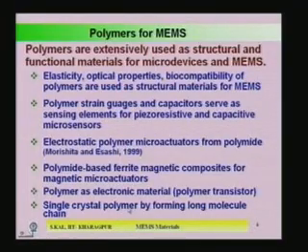Single crystal polymer is also possible. Earlier people could not think that single crystal is basically a property of semiconductor materials, but here you can have polymer as a single crystal, because you can have certain chains, a series of polymer chains that are created, and those chains are regularly repeated in a particular material. If you arrange those chains in a regular way, then it will work as a crystal. So, research is also going on how to get good quality polymer crystals.